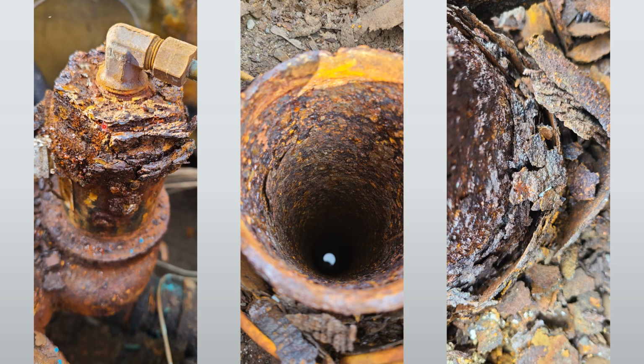Getting into a little more aggressive corrosion patterns: a mechanical line leak detector corroding off the top. This is, I believe, the worst I've ever seen. One of the reasons why I included it. I've never seen the top of a leak detector actually begin to split away. It's pretty impressive. This is another monitorizer. You can see on the inside flaking beginning to occur. So the inside of the pipe is corroded so much that we're losing metal due to flakes. I believe this is that same pipe on the outside. Just a bunch of flaking going on. Really interesting stuff.